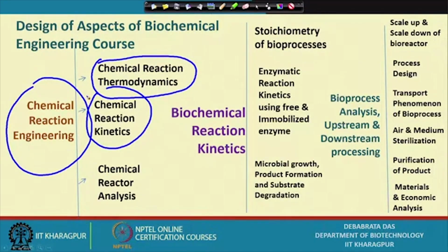To understand the process, we find different kinetic constants, develop rate equations, and simulate the equations to check their validity. This kinetics we use for reactor design, a very important part of chemical engineering, because here we find the volume of the reactor needed to get a desired amount of product. So we did a detailed analysis of the reactor.